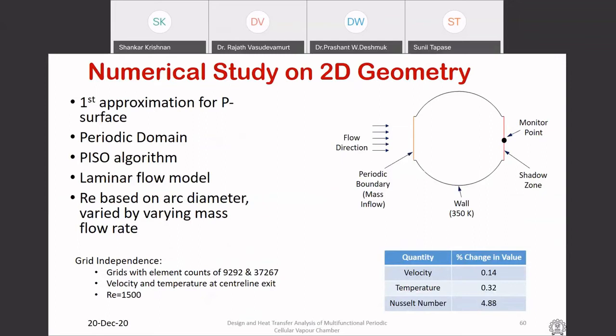But here's an example of how we make some unsteady flow. This is work done here at IIT Bombay, where this is a unit cell again, just to show the concept. We bring in some flow, and these are semicircular arcs, and that is a duct. The semicircular arcs are periodic. This is a periodic unit cell, so it gets repeated in 3D. I will show the 3D structure soon. The basic concept is that when a flow enters, the flow will separate. That means there will be dead zones on the top and the bottom.